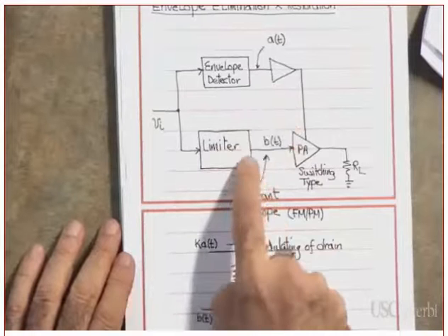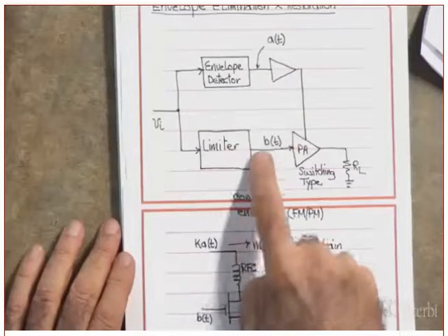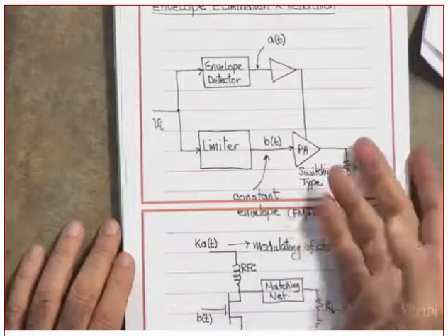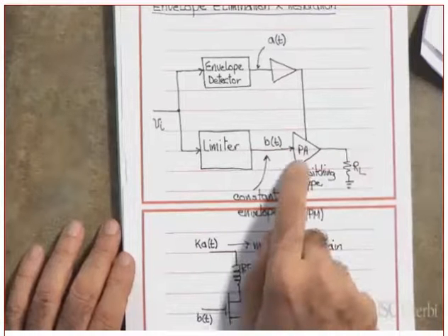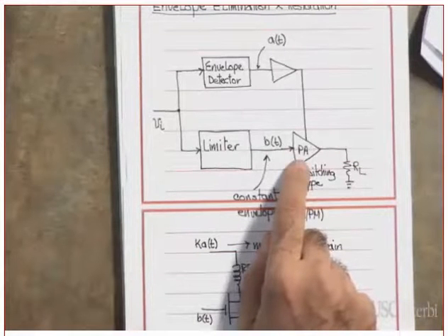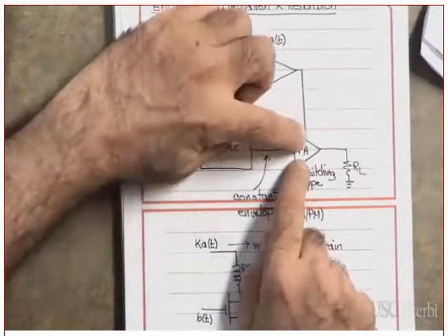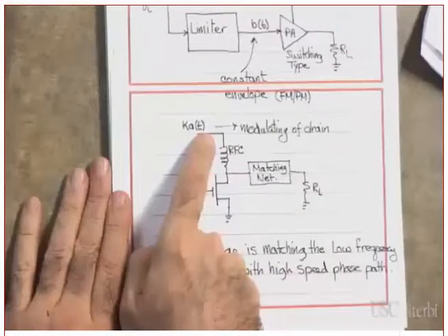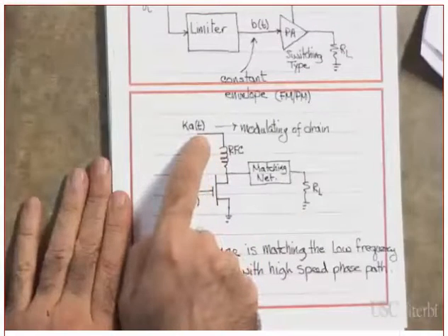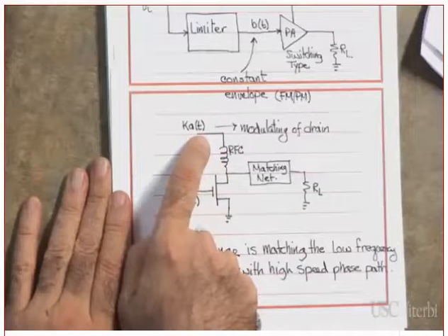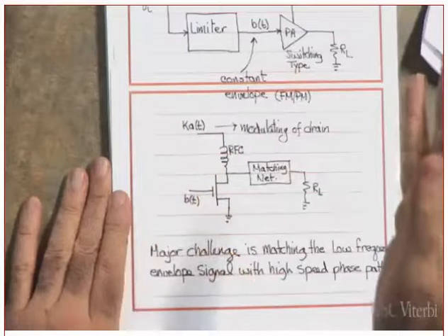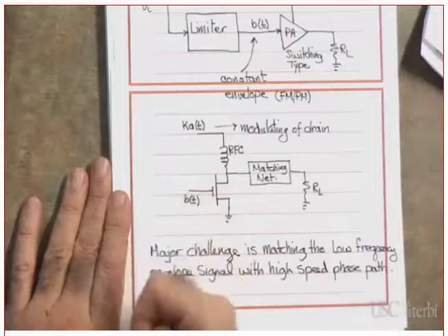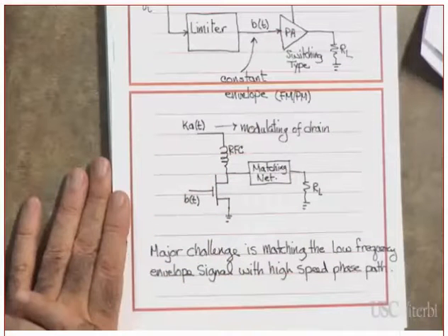Look at it. This one, by the way, is a constant envelope, FM modulated. You follow me or not? It's going to go to the power amplifier, like normal. But where is this one headed? This one is going to the power supply. In other words, this one is acting as a drain modulated power supply. I'm not sure that you followed me here or not.